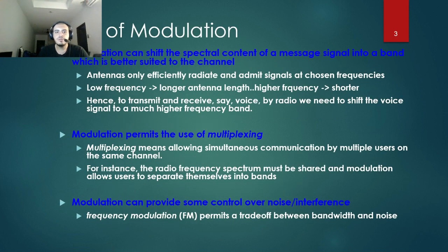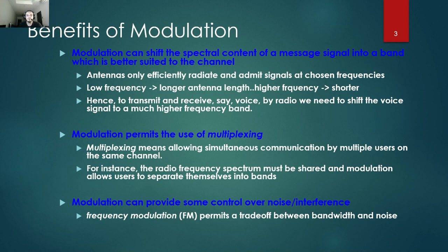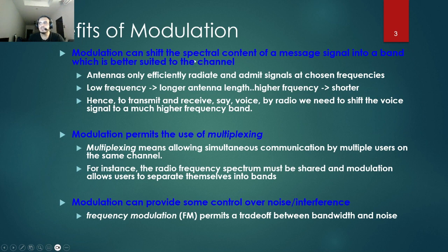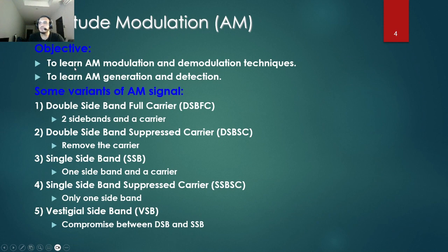Benefits of modulation. Modulation can shift the spectral content of a message signal into a band which is better suited to the channel. Another benefit is that modulation permits the use of multiplexing, and modulation can provide some control over noise and interference.